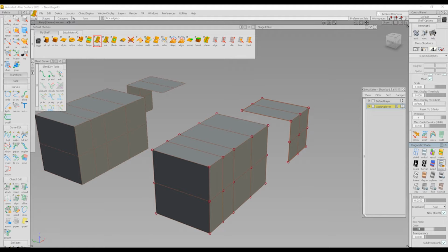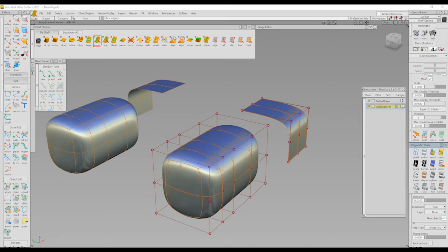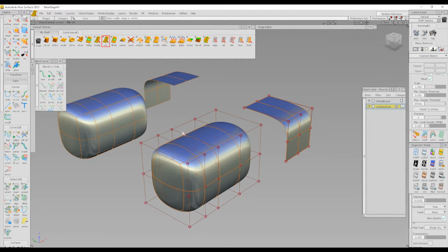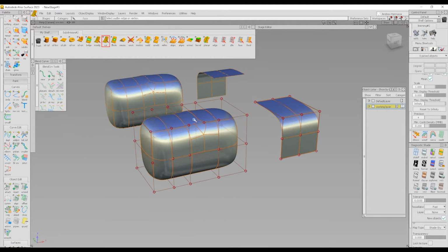Another tool I can use, which is similar to the edge loop, but instead of using an entire loop, you can just cut faces. So instead of inserting a loop throughout the whole object, I can just cut this face here and just here. And now I don't have to use the edge loop if I just wanted to insert it here. This is helpful if you basically want to draw out a shape in your object. I'll show you that in a second.